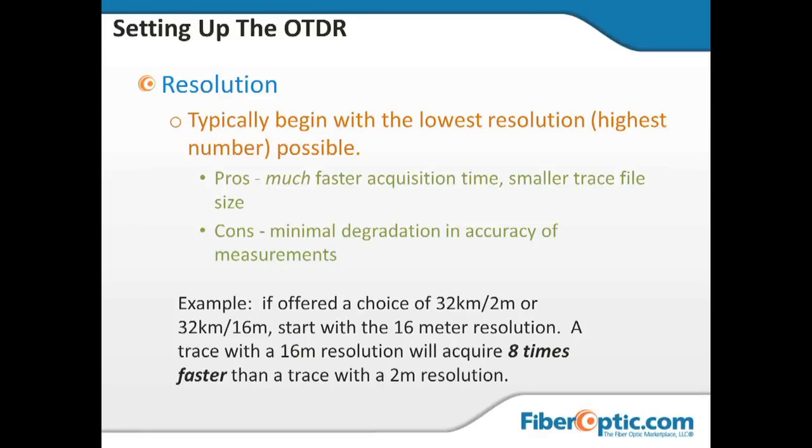That will give me a trace that is 8 times faster and about 1/8 the size when I go to store it, because I'm taking 1/8 the number of data points, is really what it comes down to. That's another simple math problem.